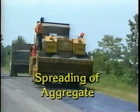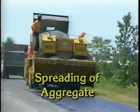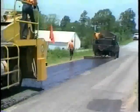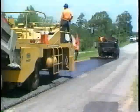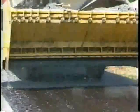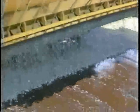The fifth step in the asphalt chip seal procedure is the spreading of aggregate. Spread the aggregate immediately after the distributor sprays the asphalt. The aggregate should be placed before the emulsion breaks. Emulsion is chocolate brown when put down, but turns black when the emulsion breaks. The water is released into the air, leaving only the asphalt.